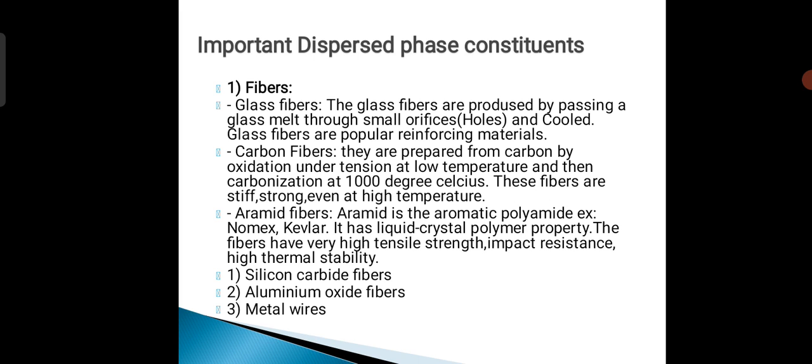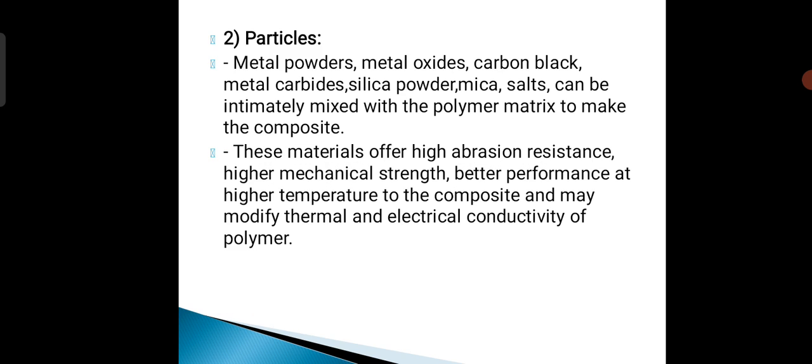Aramid fiber. Aramid fiber is an aromatic polyamide. Examples: Nomex, Kevlar. It has liquid crystal polymer property. The fibers have very high tensile strength, impact resistance, and high thermal stability. Others are silicon carbide fiber, aluminum oxide fiber, metal wires.